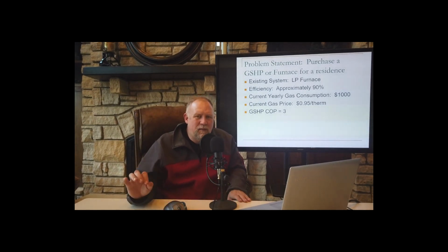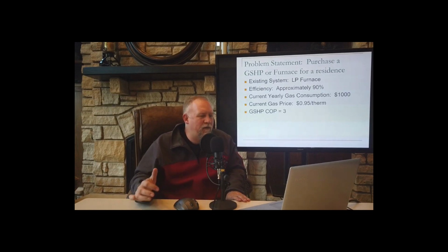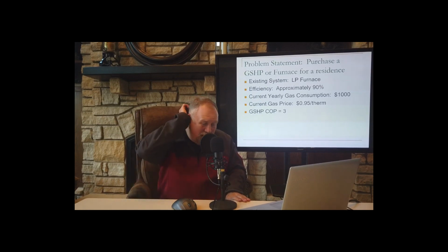And this tells me something, and it should hopefully tell all of you something about the efficiency of that particular furnace. Because they're venting it through the sidewall with PVC, that means that the temperature of that exhaust is very, very low. That tells me that this is a high efficiency furnace, high enough that it is condensing.